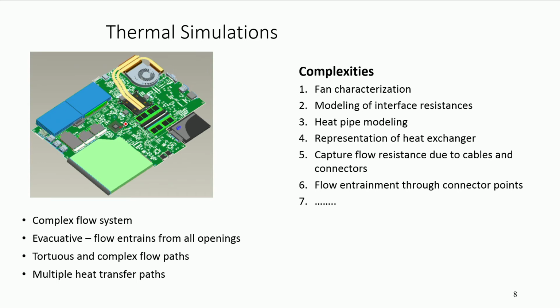But finally, what is it doing? It is acting as a very good thermal conductor. I will put an equivalent thermal conductivity that solves my problem. I do not want to get into the flow physics of what is happening inside. Representation of the heat exchanger: many a time we model the heat exchanger separately and then just put it as a heat sink with an equivalent thermal resistance.